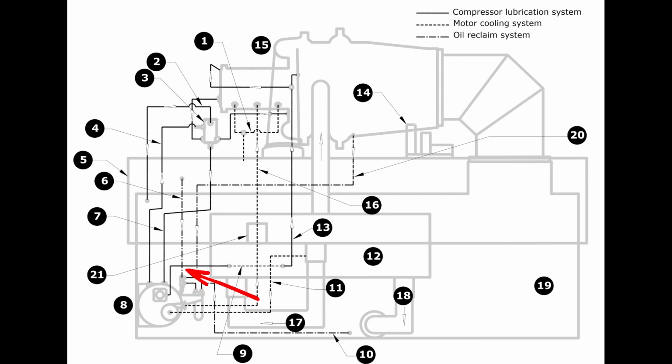Either way, in the other setup, we had three lines tied in. But if you look closely at this eductor block, we have actually four. So we've got our hot gas inlet from the condenser up here. So we're coming off that tap, coming off the top of the condenser, and then flowing into the eductor. We've got two lines right here, and then our fourth being the injection port going into our tank or our reservoir.